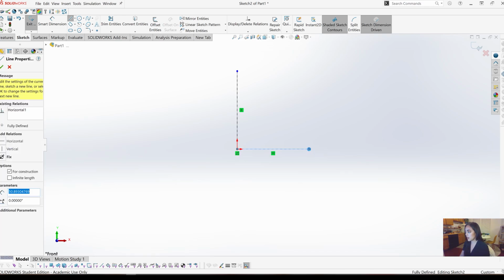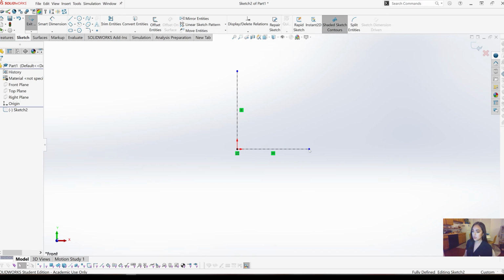The part that I'm going to quickly make today will be a revolved shape to create a pot. Actually, I have a 3D printed pot right here. So this is what we'll be wanting to create. So again, when doing a revolved solid geometry here, we want to define the center axes and then create one part of the outer shell.